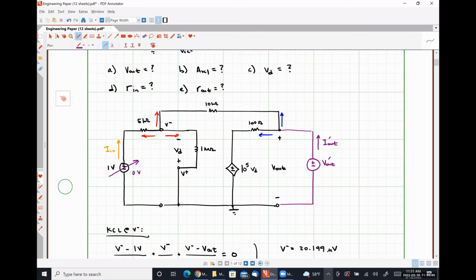Okay, so we were applying Thevenin's theorem here to calculate the resistance seen looking into the output terminals using the Thevenin voltage divided by the Norton current, which will get us literally the exact same results as if we had applied a test source of a fixed voltage and measured the test current, which I proved to the overwhelming majority of you guys in circuits 1 on multiple different occasions.